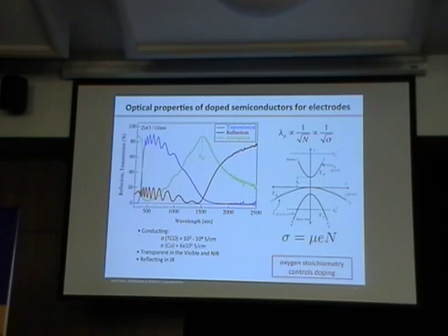If we want it as a contact, maybe we don't want to dope it so heavily because that might cause recombination. But we wanted to provide these other properties that Cephas just enunciated for us, which is we want them to pass the carrier that we want to harvest at that particular electrode and contact pair, and reject the one that we don't.